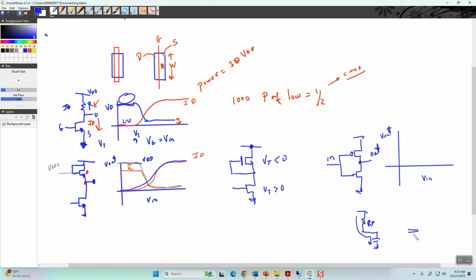And then when the PMOS is off and the NMOS is conducting, you discharge. Now, of course, as it's switching through, they're both on. This is just more the endpoints. What you can see is that this is just like a regular RC circuit. Now there's a lot of capacitances and a lot of complexities in the RN and the RP, but really, you can understand this with just first order RC, right? Because you just lump all the C's together.